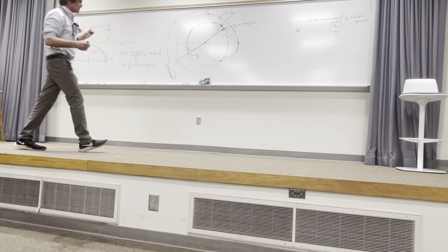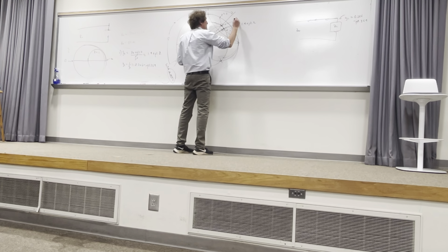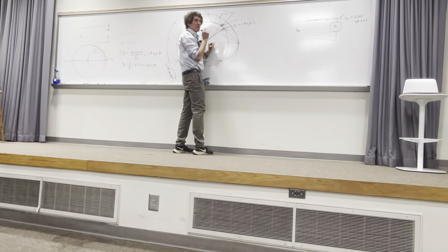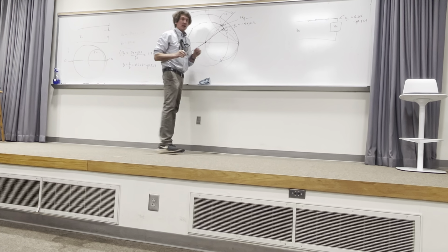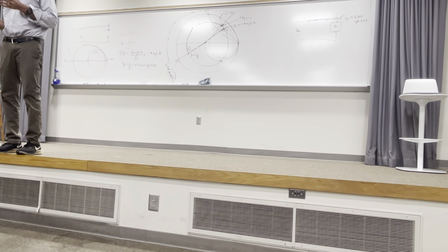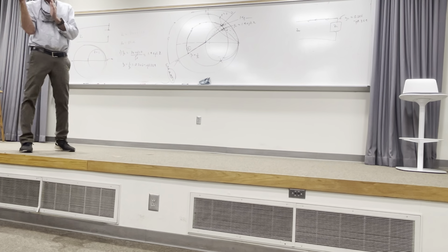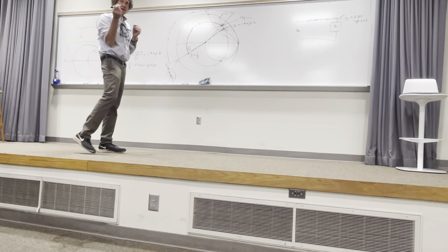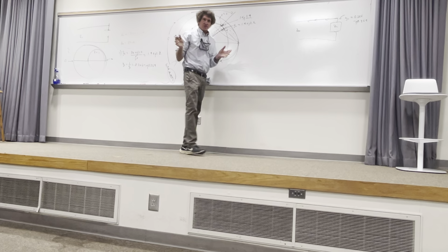Now we get the value of this. I know the real part's 1, but what is the imaginary part at this point? This is going to be how far we move in the value. It's going to be 1 plus j what? 1.85? I want to make sure everybody sees this. I've got a 1.85. Take a look. You're going to get variance. It's just inevitable. 1.9. I got 1.9, 1.85. I got 1.85. All right, and you will see some slop depending on how accurate you drew the circle and how sharp your pencil point is. All right, 1.9 is good for this discussion. Got it?